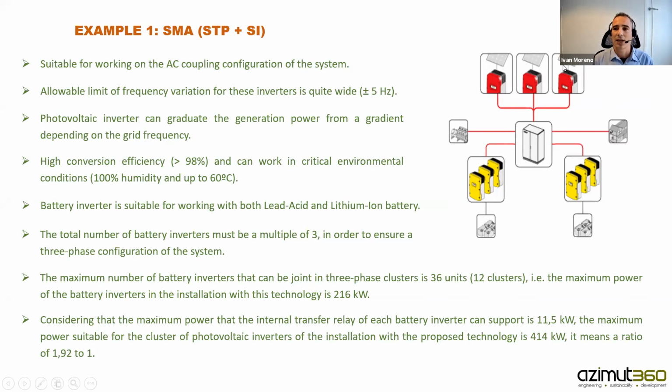This means that these inverters have the off-grid mode, which is that the battery inverters modulate the production of the PV plant by increasing or decreasing the frequency, so that the PV inverters can reduce if the frequency is rising from 50 Hz to 51, 52. The PV inverters know they have a ramp down to go from 100% to 0% of their production.